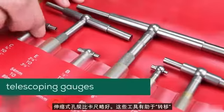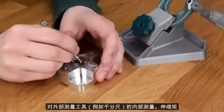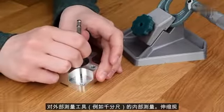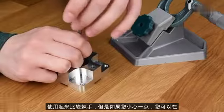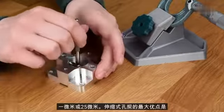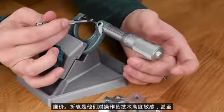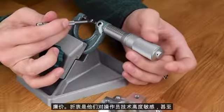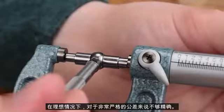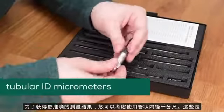Slightly better than calipers are telescoping bore gauges. These tools help transfer an inside measurement to an outside measuring tool like micrometers. Telescoping gauges are tricky to use, but if you're careful, you can get a measurement that repeats within 1 thou or 25 microns. The biggest advantage of telescoping bore gauges is that they are cheap. The trade-off is that they are highly sensitive to operator technique, and even under ideal circumstances, aren't accurate enough for very tight tolerances.